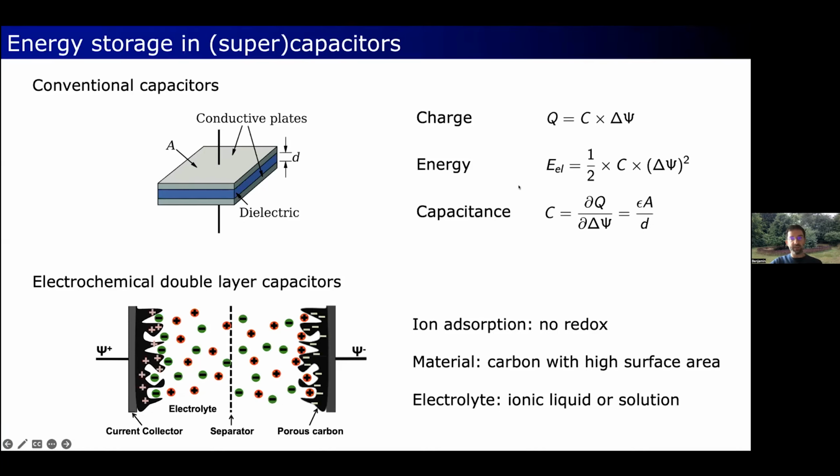And the capacitance can be defined either as the integral capacitance, as I've just mentioned, or as the differential capacitance, which is the derivative of the charge on the electrode with respect to voltage. In the case of a standard capacitor, both the integral and differential capacitance coincide, and they are equal to this quantity here, which is the product of the permittivity of the dielectric medium and the area of the conducting plates, and it's inversely proportional to the distance between the two electrodes.